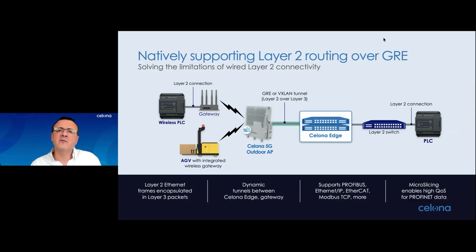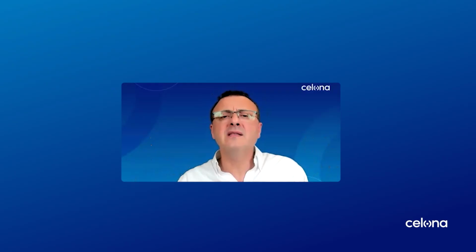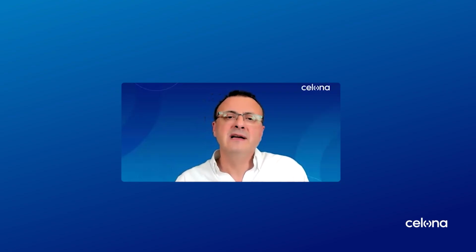This is particularly powerful for mobile use cases like AGVs with integrated gateways, where you need to preserve this deterministic control behavior while allowing the endpoints to move freely. And because this runs over private 5G, we can combine it with microslicing and QoS enforcement and ensure that all the prioritization and quality requirements are met. The key point here is that we are not forcing OT systems to adapt to cellular. We are really adapting the cellular network to the realities of the industrial IoT system.